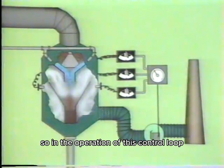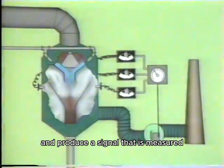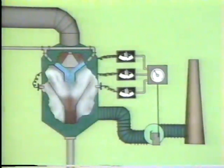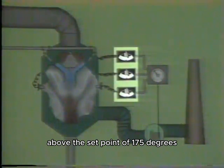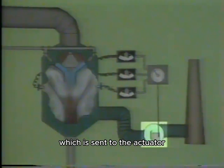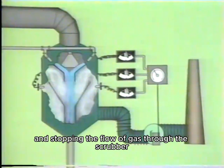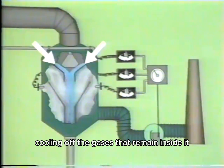So in the operation of this control loop, the temperature probes sense the temperature of the cleaned gas and produce a signal that is measured at the transmitters. The transmitters convert the temperature indications to signals that are sent to the controller. If any one of these input signals indicates a temperature above the set point of 175 degrees, the controller produces a corrective output signal, which is sent to the actuator. The actuator adjusts a hydraulic coupling, disengaging the ID fan from its motor and stopping the flow of gas through the scrubber. Water continues to flow through the scrubber, cooling off the gases that remain inside it.